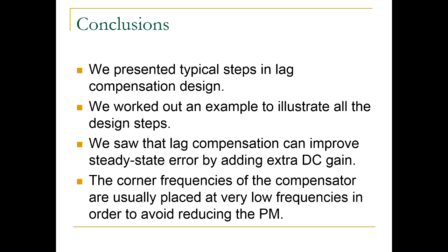And all of these things you are asking would have an effect on all the sensitivities. So at the end of the day, you have to plot all your sensitivity transfer functions, Bode diagrams, and see what you get. And then if there are any peaks, any sort of undesirable behaviors, you may say, well, in the beginning, I didn't want this to be part of the specs. But now I can see that this is important. So you go back and you revise your specs, right? But it does affect everything, really.